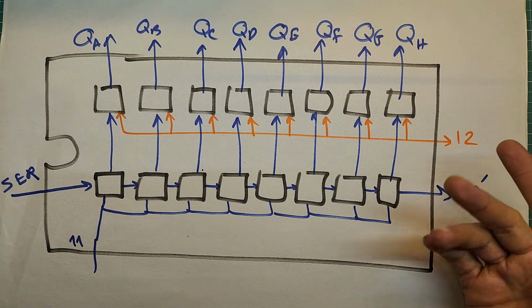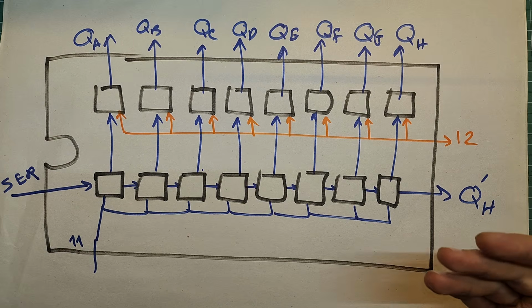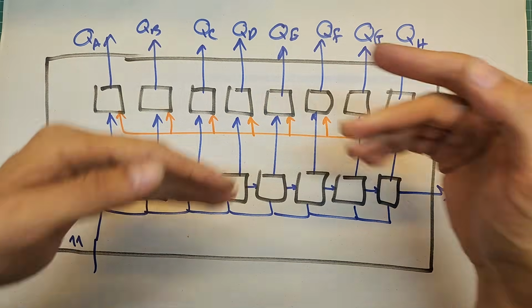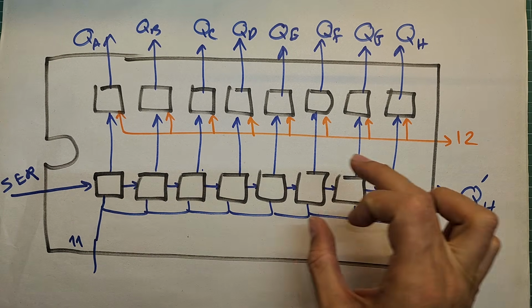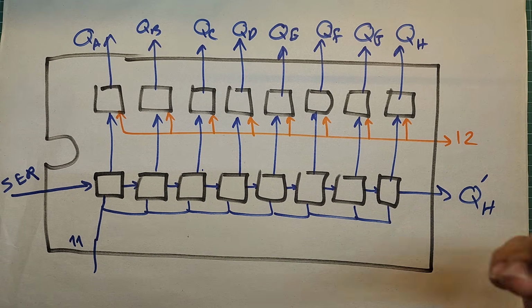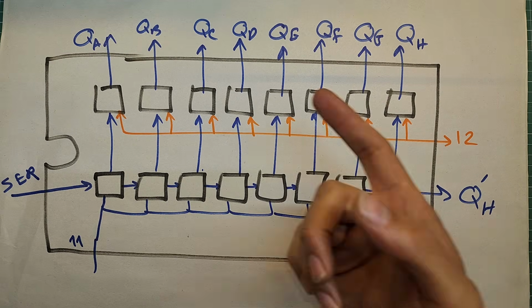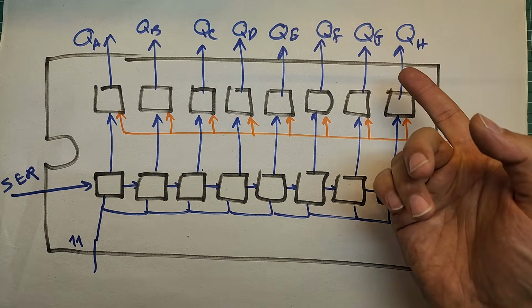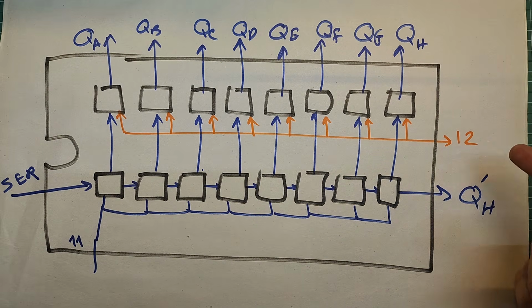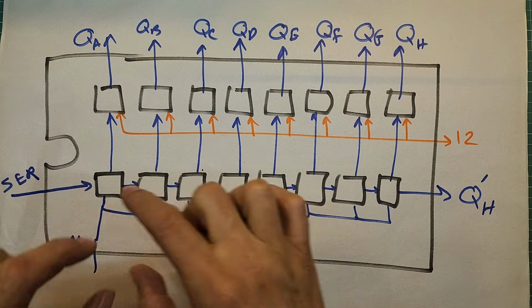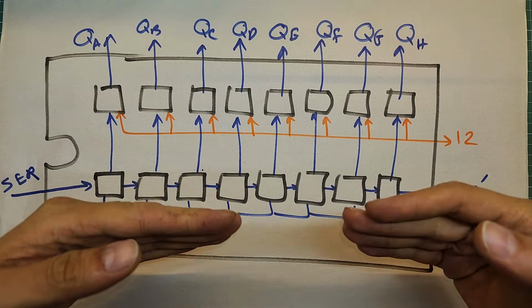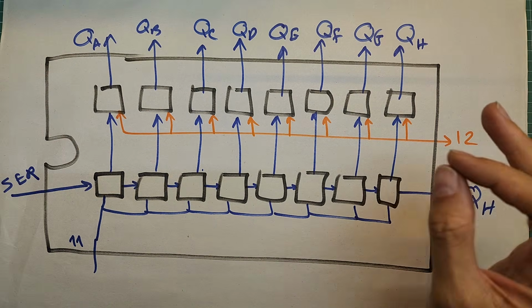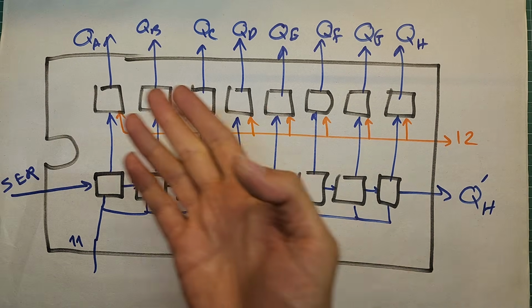The next point is pin 12, which is used to transfer data from the memory to the output. If this pin didn't exist, when the microcontroller was changing the value, we would temporarily see undefined values and unpredictable patterns on the 7-segment display, and that is not nice at all. But this pin allows the microcontroller to firstly apply all its desired changes to the IC's memory, and then with a single clock to pin 12, transfer the changed value to the output. With this, there will be no more undefined and ugly patterns on the output.